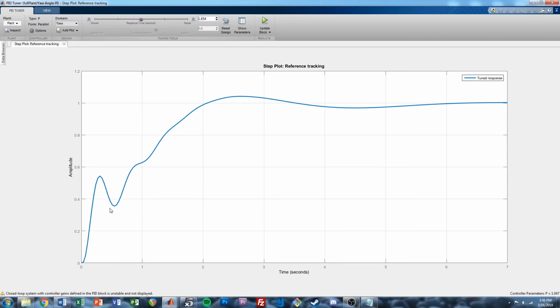So you get that initial turn due to the yawing moment, and then you create sideslip, which manifests itself in changing a roll attitude. The rest of it, the slower response here, is that change in yaw angle you get just from the fact that you're turning. So that's kind of why you have this multimodal step response going on here.